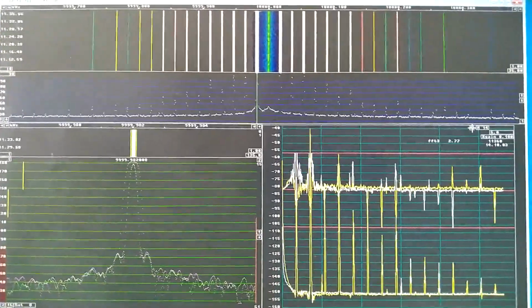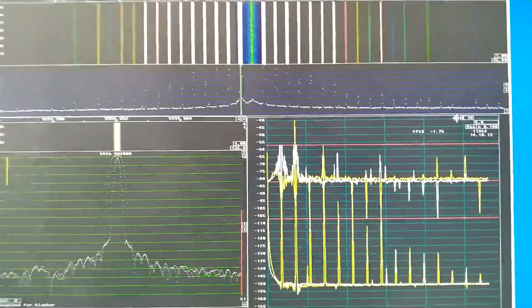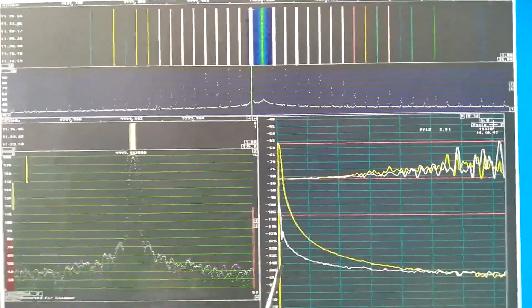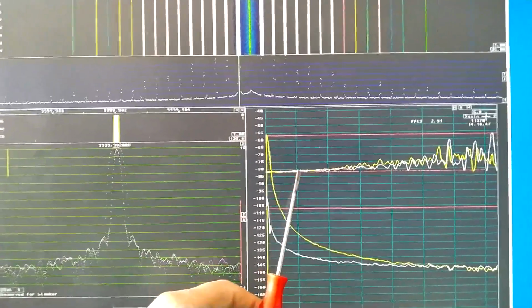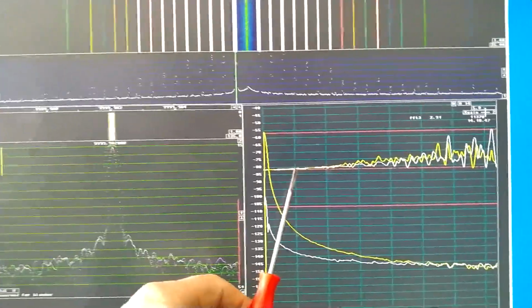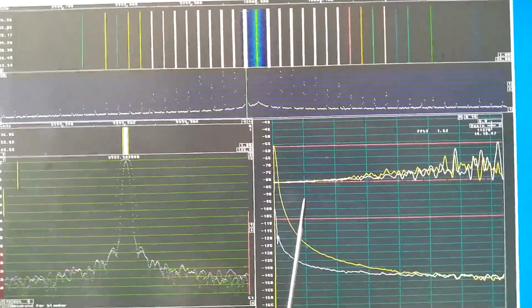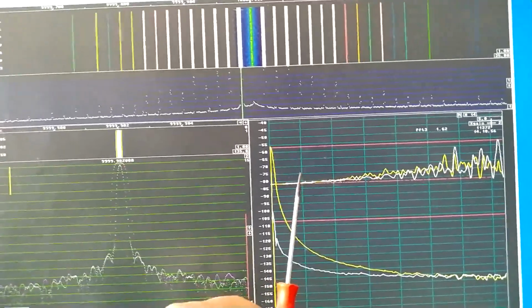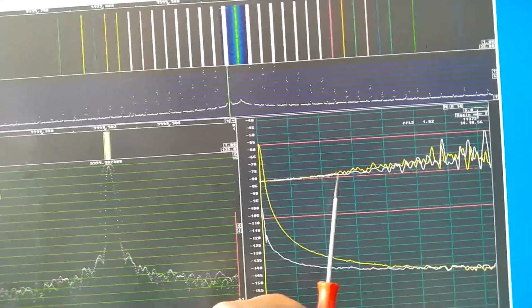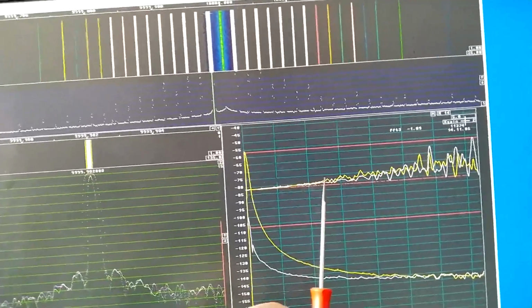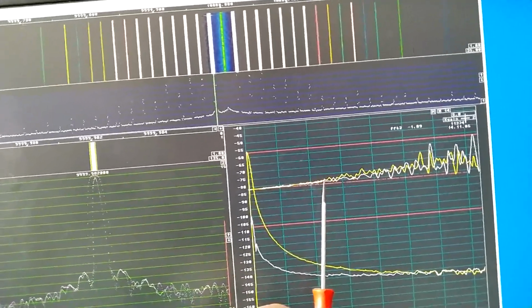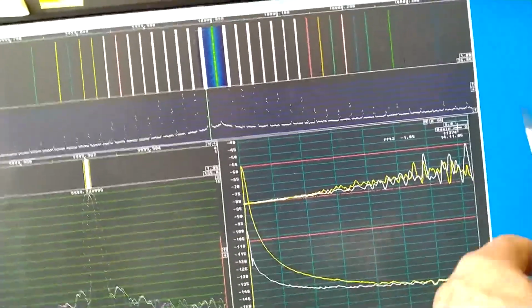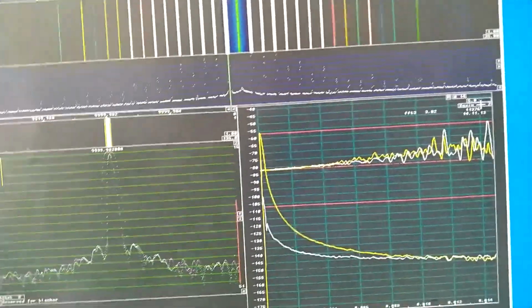I will expand the spectrum to see what to say about that. It's clear that at very low frequencies, there is no correlation. That's the range where the noise from the oscillator dominates. Going a little bit above, up to 5 Hertz, there is a correlated signal. It means it is leakage from the strong correlated signal up here somewhere outside.